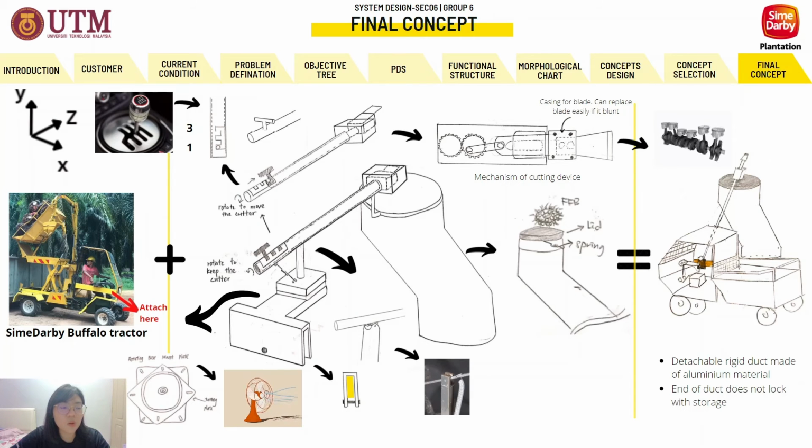After driving near to a young oil palm tree, the worker needs to work on the handle area in this device. This will allow the chisel to have an in and out motion in the Z direction from the safety box. The handle area is similar to the manual car handle, where there will be one T-shaped handle that is connected to the rope. The T-shaped rope will be slotted into this hollow compartment, which is a flipped E alphabet shape. When the worker rotates the handle to the right-hand side along the Z direction, it will allow the T-shape to slip into a freeway, which he could push the whole chisel rope upward in the same direction to position 3.